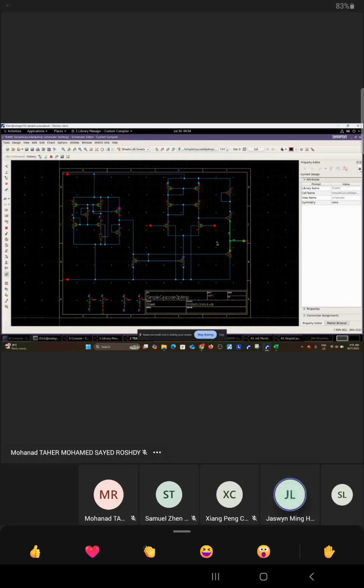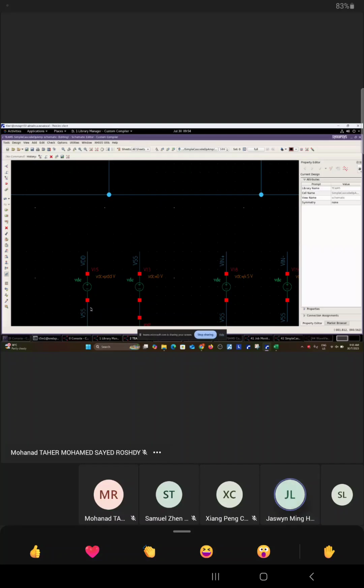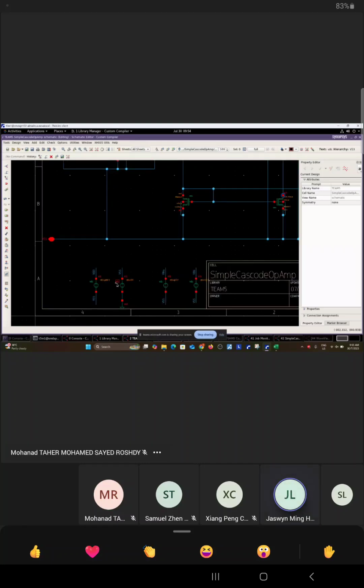Okay, so you can see, right? Yeah, they can see it. Okay, this is... So you simply do transient, you just zoom into where you put your, previously you created DC voltage for your common mode voltage, right? Yeah, you zoom in there. Instead of creating a DC voltage now, you're going to create an AC voltage.